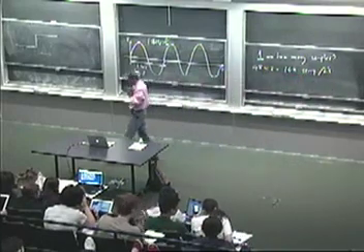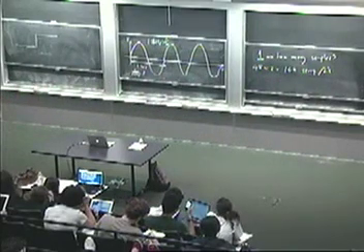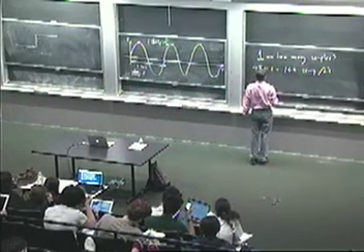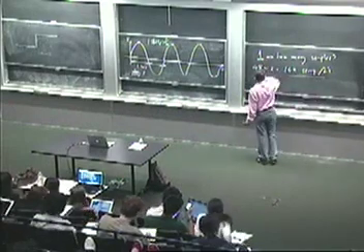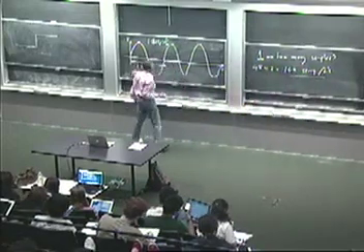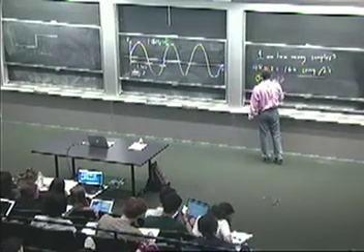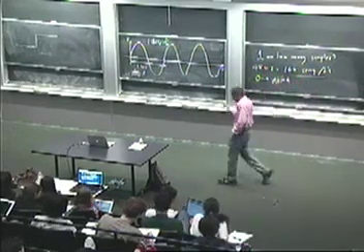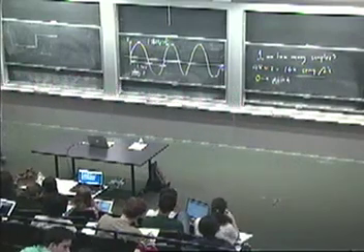Now, to transmit a 0, I could do a bunch of different things. I could decide to keep the channel silent. If I do that, it's called on-off keying, and that's what we're using here. So if we decide to use 144 samples per bit, then we represent a 1 as 144 samples, which corresponds to 3 of these. And then we represent a 0 as nothing. So we don't send anything. This is called on-off keying, because we send on for 1, where we send a sinusoid, and for sending a 0 bit, we send nothing.